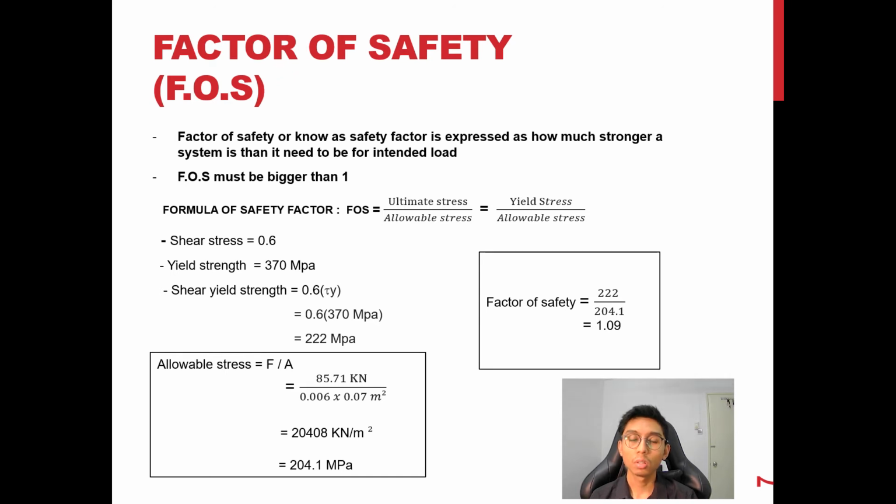Factor of safety, also known as safety factor, is expressed as how much stronger a system is than it needs to be for an intended load, or in easier words, how much load it can bear before failure. In our project, we calculate the factor of safety of the screwdriver. We can calculate it using this formula, which is ultimate stress over allowable stress, or yield stress over allowable stress, which is the same.